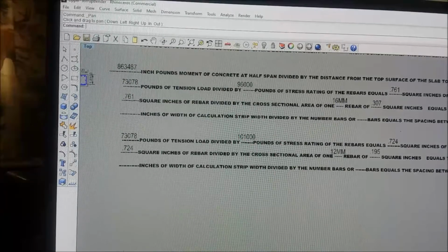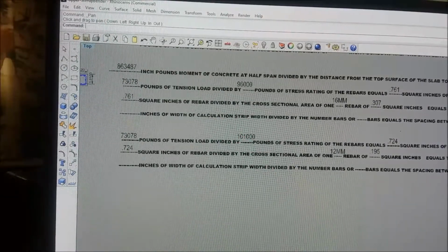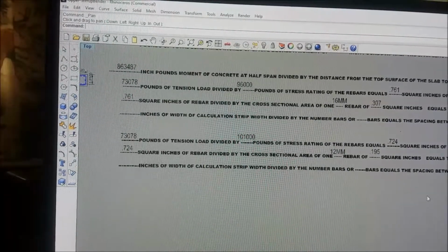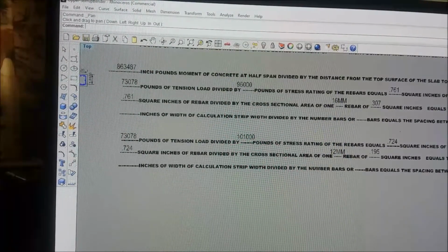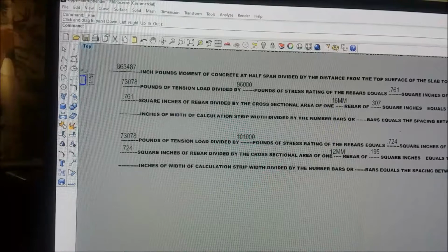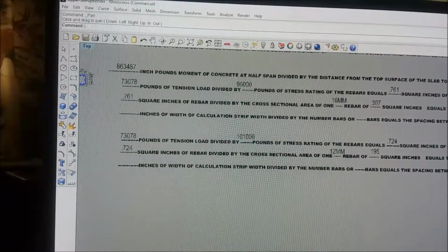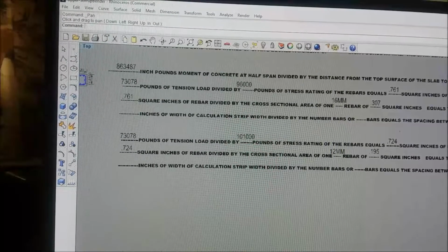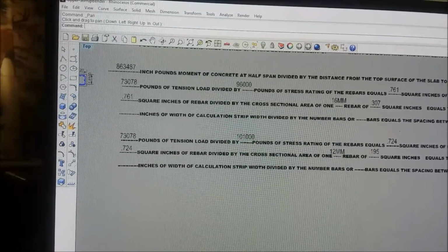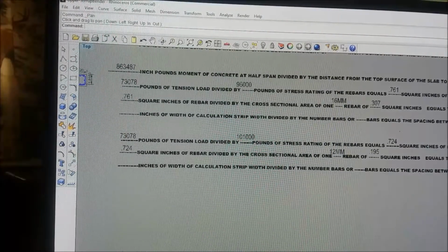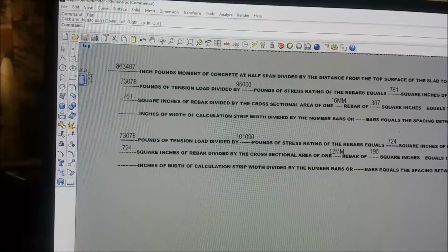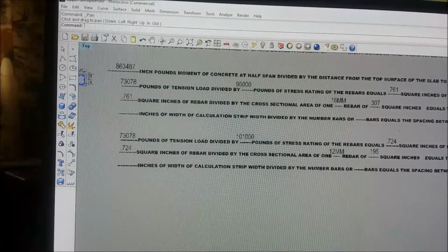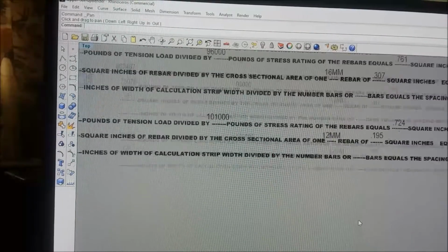Conclusion. We already did that, actually. Conclusion is that you get more steel in your beam, and ultimately a stronger beam with the 16 millimeter rebar, because you round it up a lot more to get to the next higher bar than you did with the 12. You round it up much less, only about half as much, with the 12.